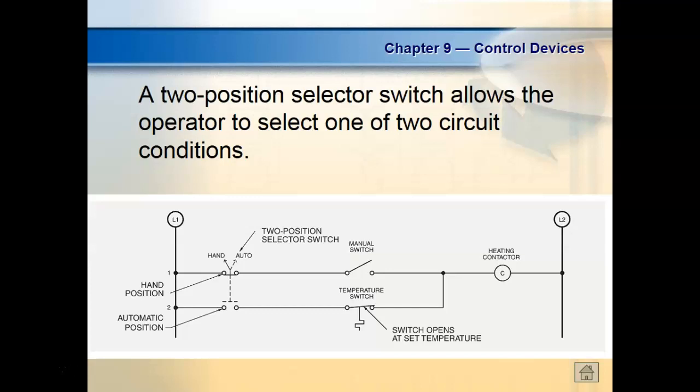You understand that? So what determines how it was, whoever wires the circuit up and bought it, okay, I need a two position, let's just do a two position switch that does this. You don't buy an auto selector switch. You don't buy a manual selector switch. You buy a selector switch, and then you wire it to do what you want it to do, and then you put a legend plate up there that tells the operator what positions of the thing does, right? Does that make sense? Same switch, just has a different legend plate on it, and the contacts are labeled different.